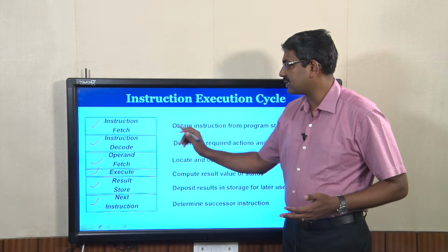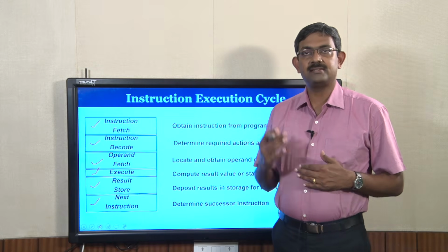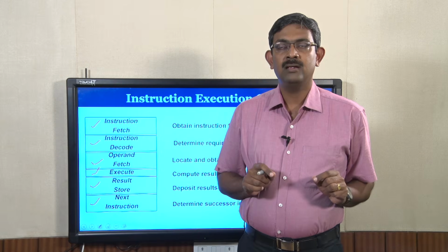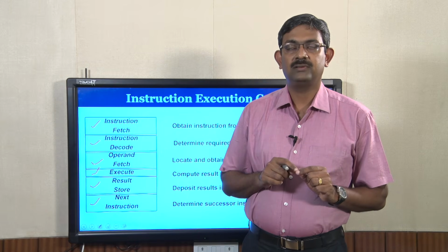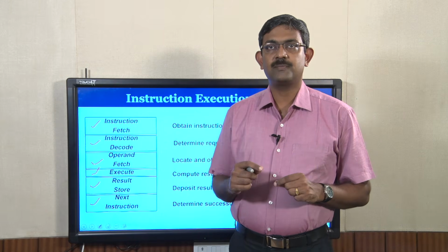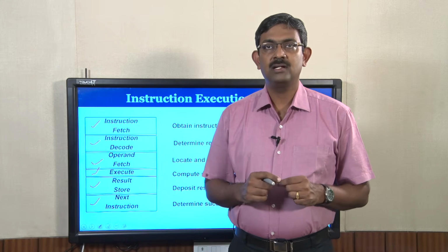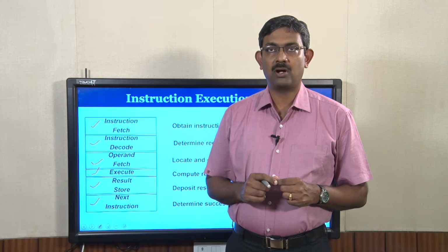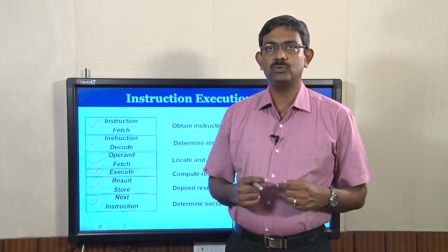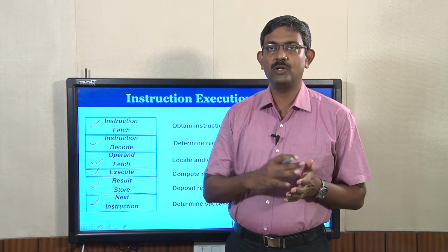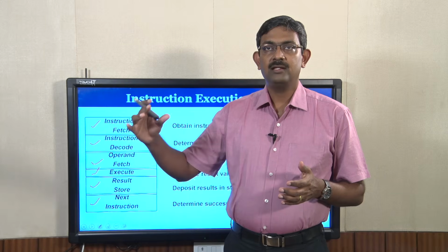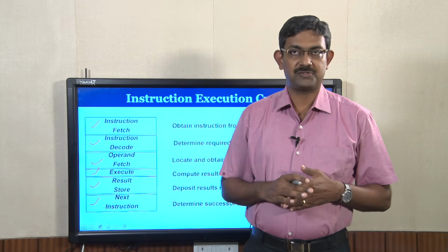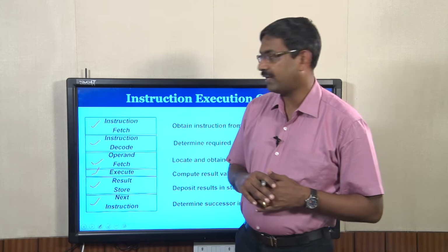When you talk about instruction fetch, it is a stage in which an instruction is brought from the memory and placed inside the processor. To facilitate this, the processor will issue the address from which the instruction is to be fetched, and that is typically the content of program counter. So, program counter issues the address and this will go into memory. From there, the addressed word, the addressed instruction is being brought into the processor, and that is called instruction fetch.